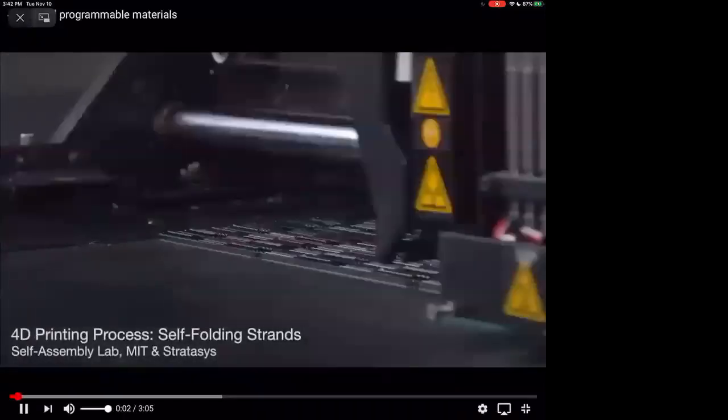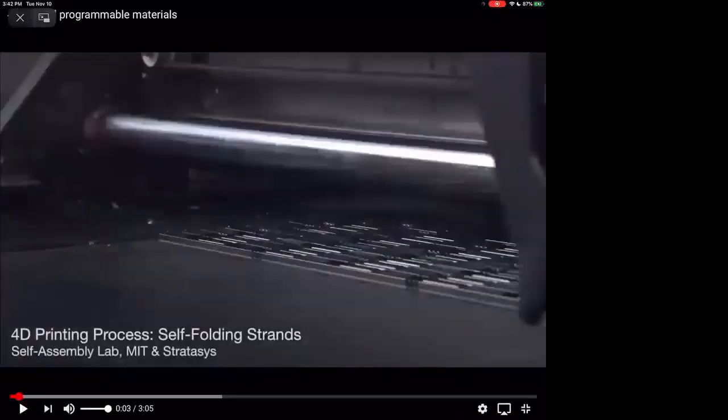Okay, first off, we can see the printing technology. It's in high speed, but this is PolyJet printing or material jetting. And so this is printed on a Connex printer and made by Stratasys. And what this is, it's a rigid material and a water swellable material. So this is a 3D printed construction that they're going to put in water, and part of it is going to expand and cause this folding that you'll see. So this is printed on a commercial printer, and they just use different inks to get the function that they want.